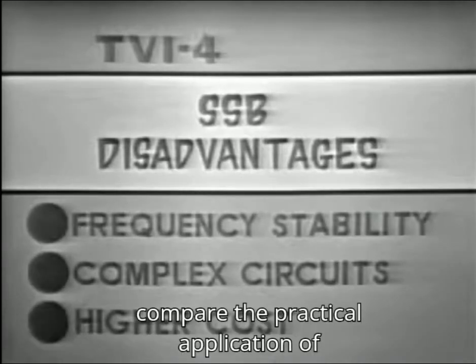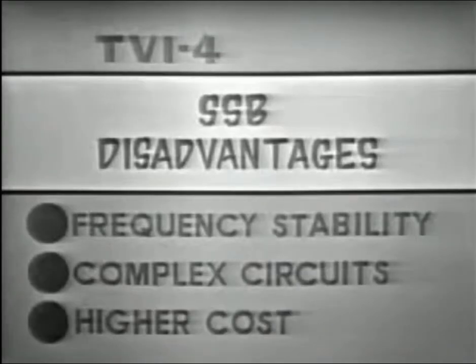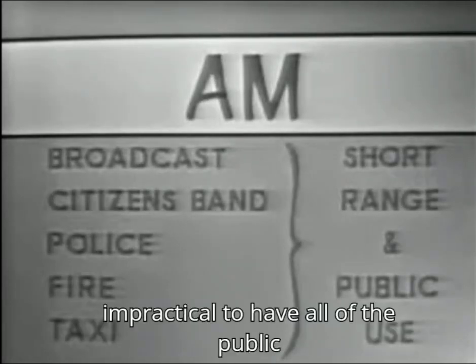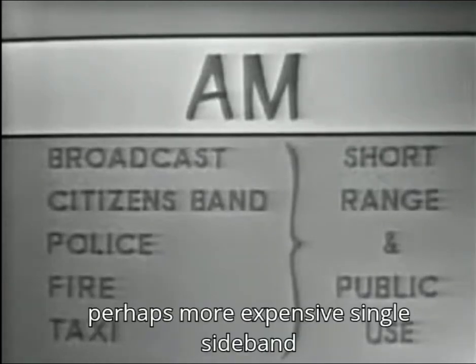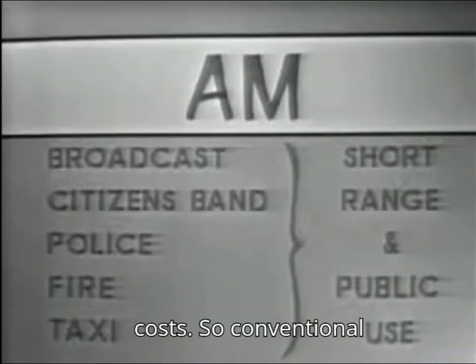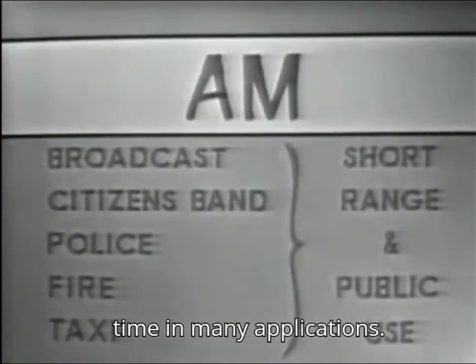But let's compare the practical application of conventional AM and single sideband. For short-range communications for the general public, it would be impractical to have all of the public turn in their AM equipment for perhaps more expensive single sideband equipment, which might require more skill in tuning and higher maintenance costs. So conventional AM will be with us for quite some time in many applications.